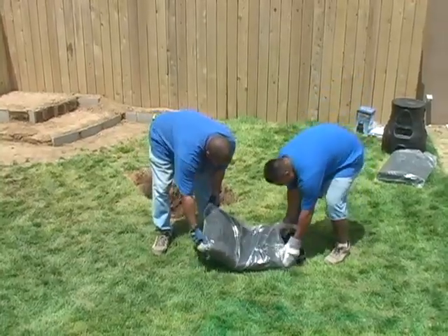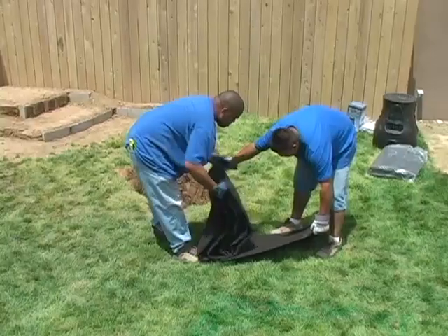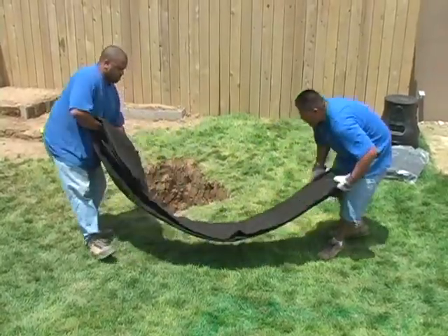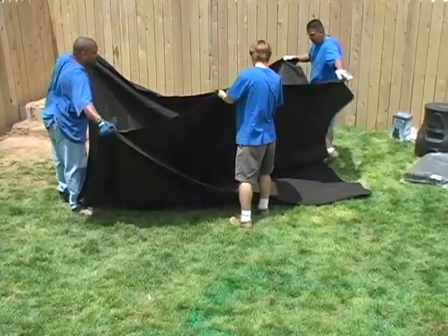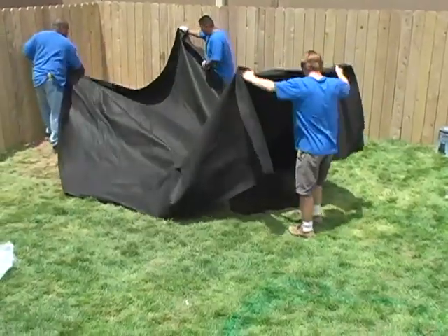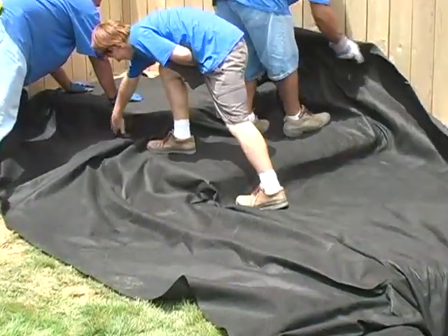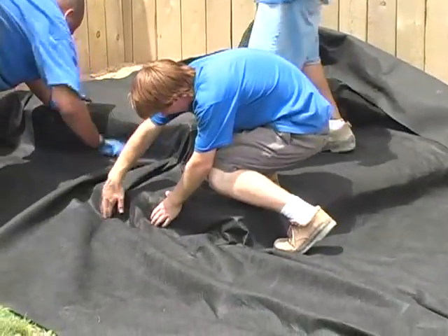Remove the underlayment from its packaging. Geotextile fabric protects and extends the life of the liner. Place the underlayment over the basin and waterfall runway so that it covers the entire watercourse. It's best to start at the bottom of the basin and work your way up, smoothing wrinkles and folds.